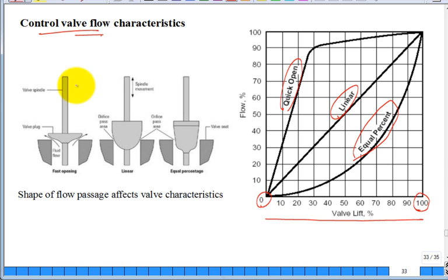So it'd be the position of some stem that pushes down to seal it. So the characteristic of how much flow you have for the same pressure pushing it across a valve and the valve stem lift depends on the passage characteristics, how it opens up. And so here's just a crude illustration showing maybe a different design of how that passage will open up as the valve lifts versus how it'll open up.